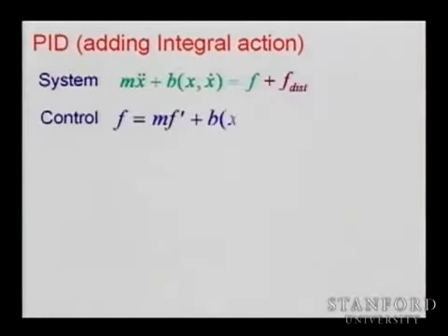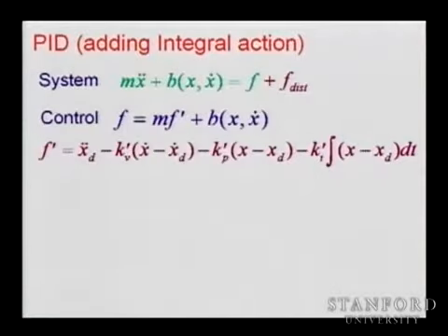All right. Okay, why by adding I can we remove that error? Because over time the I grows large if you have a steady state error, and it'll correct for that. Yeah, basically you detect the error, and as long as you have an error, you are adding. So essentially, the idea is now your f prime will include an additional term that magnifies this error with some gain, and keep magnifying and keep adding until you overcome that disturbance.